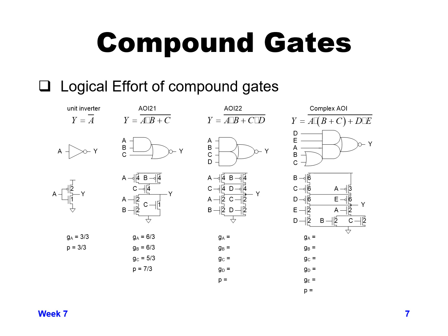So if you go through this gate, the A, B, C, and D inputs are all effectively the same as each other as far as size goes. You have one PMOS of size 4, one NMOS of size 2, so it gives us 6/3 as our normalization factor, and so all of them should be 6/3. So I'll go through that quickly, and the value of P is the total sum of capacitance on our output Y. So we have two PMOSs of size 4, two NMOSs of size 2, so that gives us 12, and 12/3 is our propagation delay.